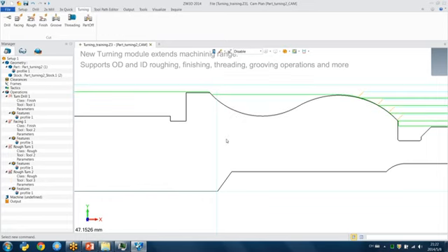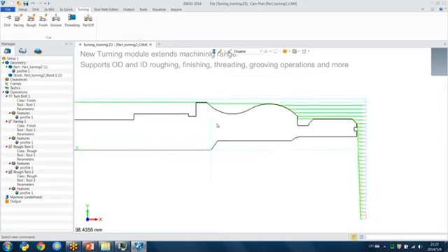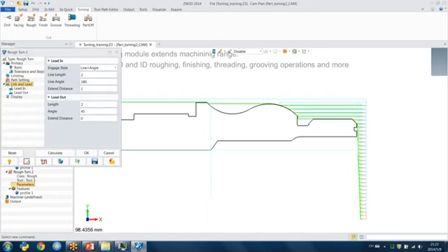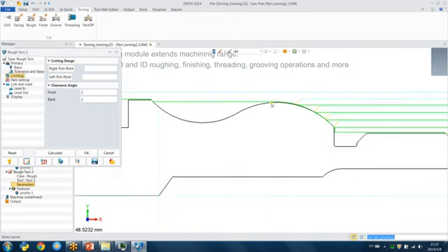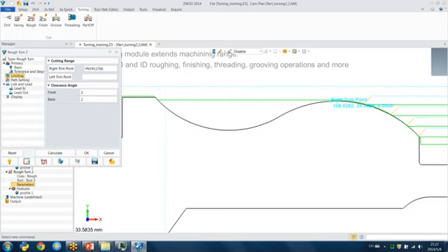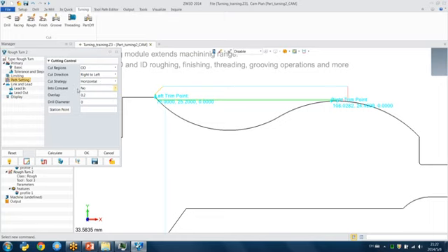With tool 3, calculate, still the same. So I need to change the parameters. Limited right point. Just start here. I want to rough here, from the left point to here. So you can find just correct one line. With the path setting, I need to change into concave. Yes. And calculate. So you can find the tools can get inside.